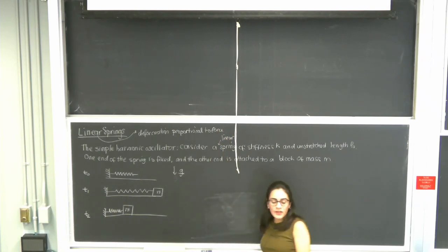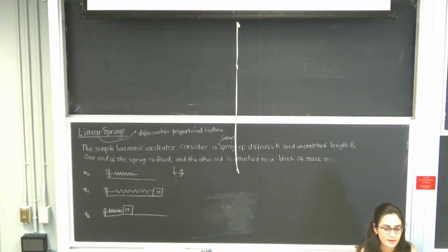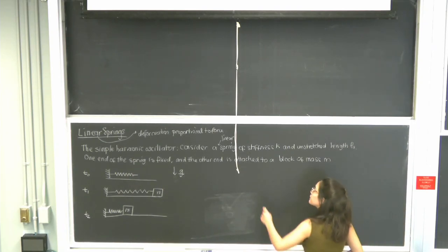Raise your hand if you've taken mechanics of materials. Yeah. So in this class, did you learn about Hooke's law, linear materials? You studied materials in the elastic region, the linear region. So if you apply a force, they're going to deform. Once you remove the force, they're going to go back to their undeformed state, and the deformation is going to be proportional to the force. That's Hooke's law.